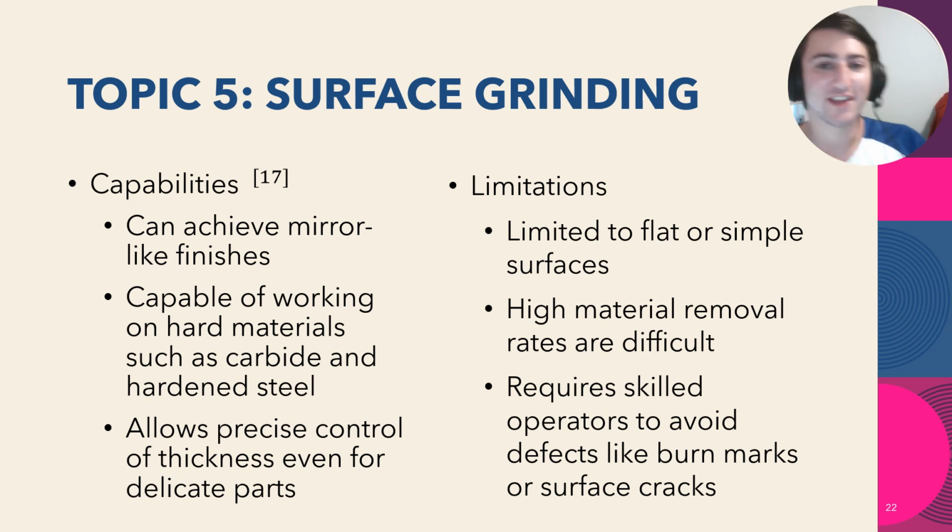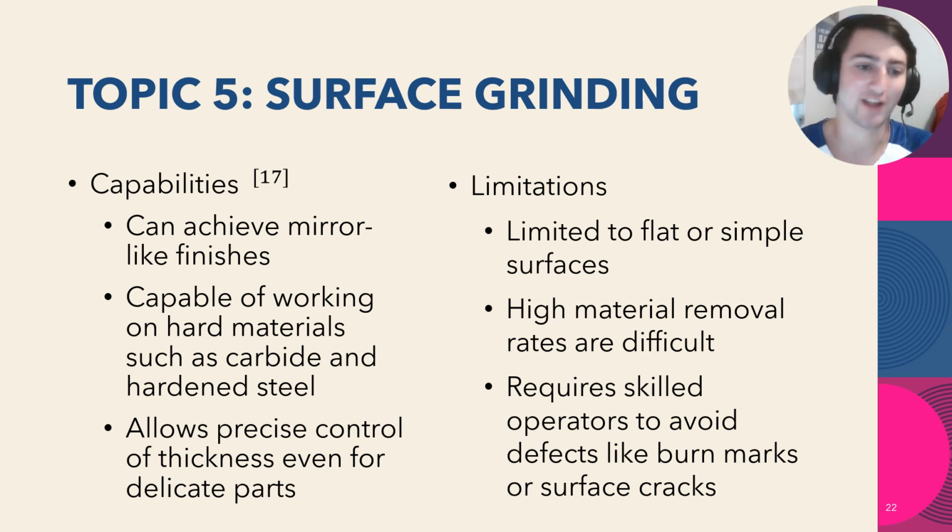Some of the capabilities of surface grinding include achieving a mirror-like finish on products. It's also capable of working on hard materials, even hardened steel. It also allows for precise control of thickness for delicate parts.